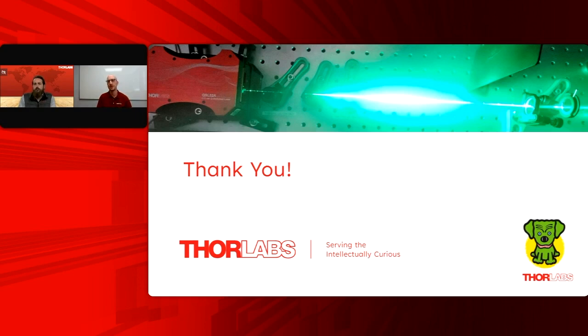So there typically is a little bit of taper associated with drilling a hole to a given depth with one of these lasers. There's novel applications where people drill through transparent materials with femtosecond pulses, where they can get truly untapered holes with large aspect ratios.